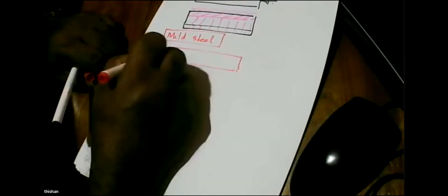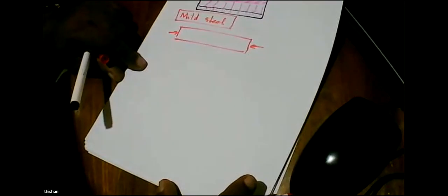So when you use mild steel and apply the stress, sometime later they found out that due to the relaxation of steel, the pre-stress vanishes. So initially you can apply pre-stress. After some time you don't get pre-stress, because due to relaxation of steel, the pre-stress vanishes.